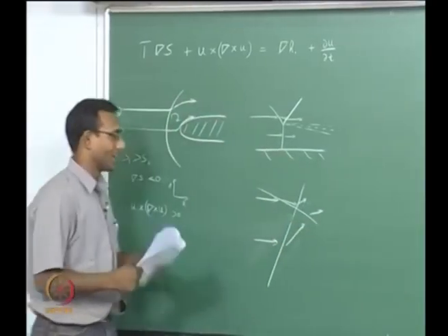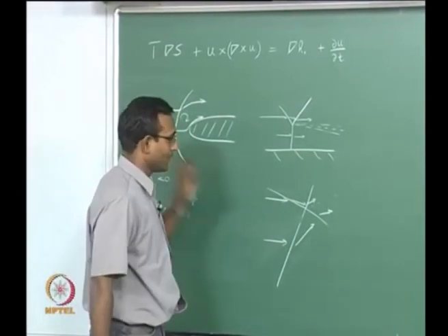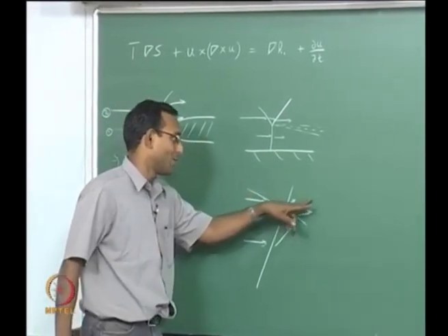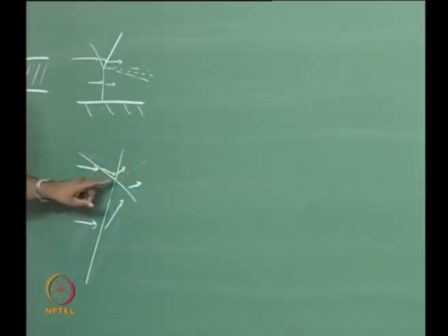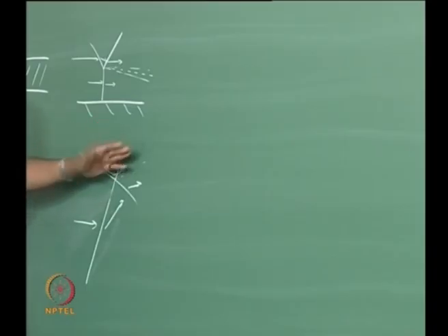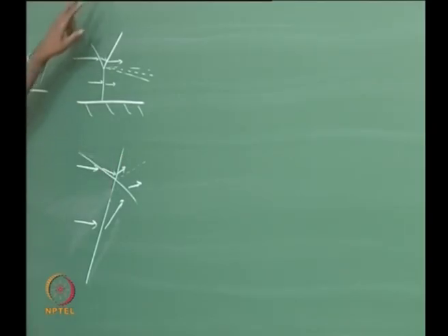If I think of this particular case also, I can now show that this line will have vorticity across. Why? I am having different entropies across these two lines. Everywhere else it is processed by the same shock. If I pick one streamline here and one streamline here, exactly the same entropy. Del S will be 0 there. Del H is also 0, it is steady, so there is no vorticity there.